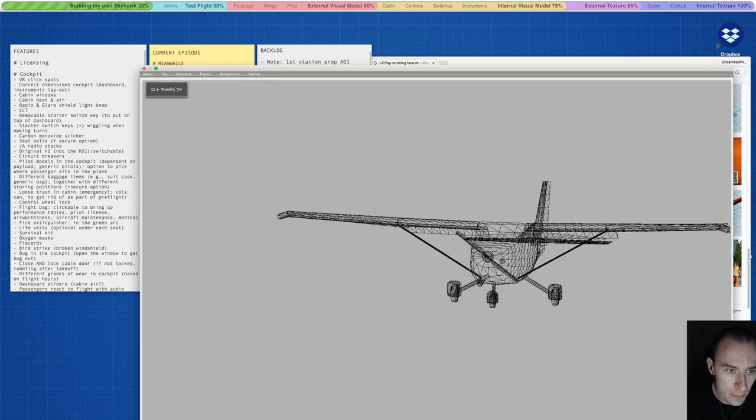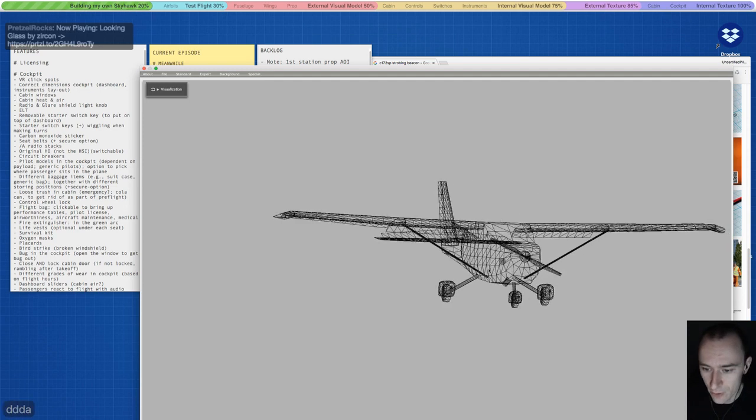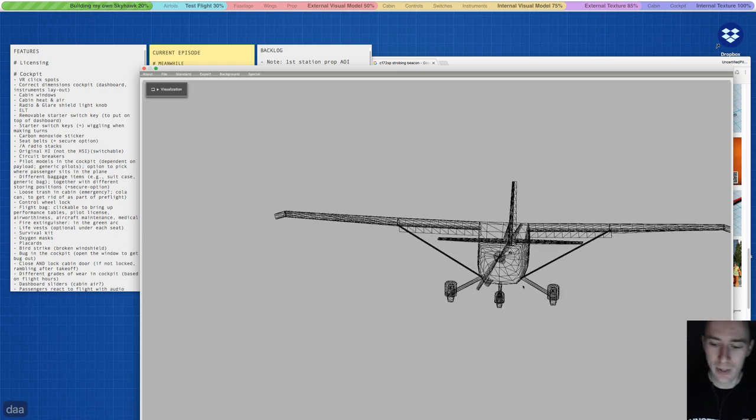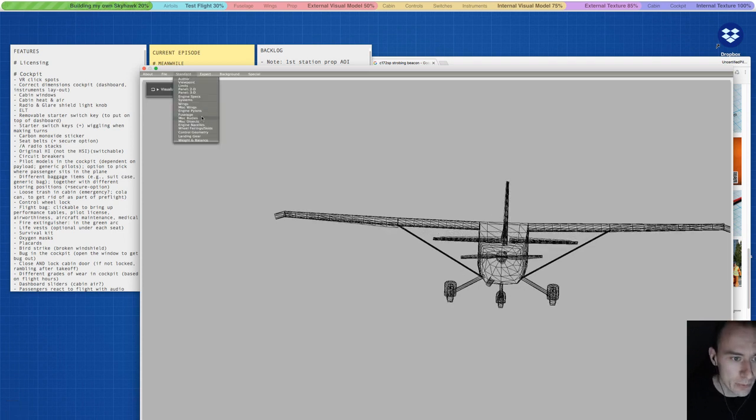That's the exhaust pipe. The difference between a body and an object is that objects don't count in the aerodynamic rendering in X-Plane. So that's where we're going to put our visual model of the Skyhawk on top of this one, so we can see it, but it's not included in the aerodynamic calculation in X-Plane. The bodies, well, we played around a bit and we thought the exhaust pipe is kind of significant, not that much, so we added it to our frame. It might be more of a nuisance during the test flight, and we need to remove it anyways, but that's what we did.